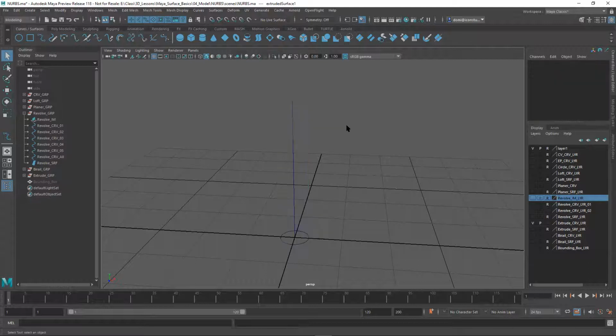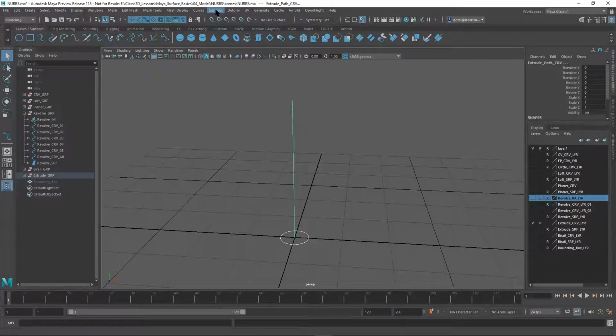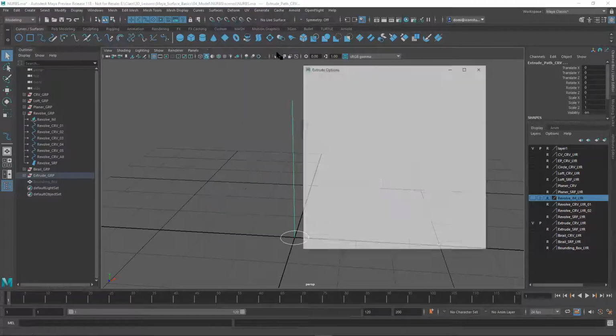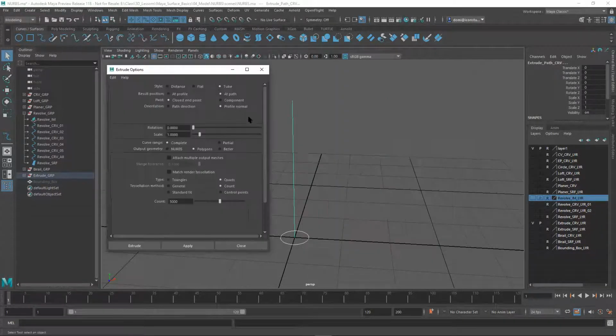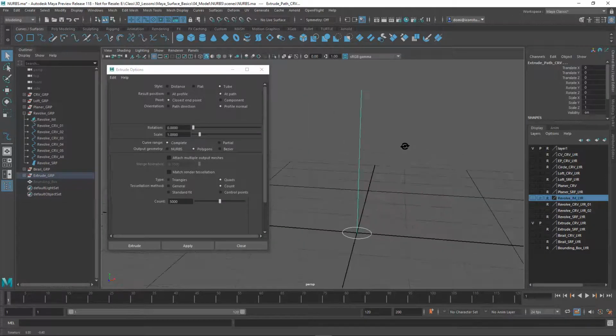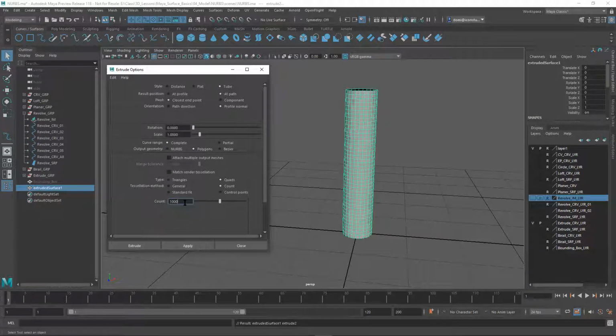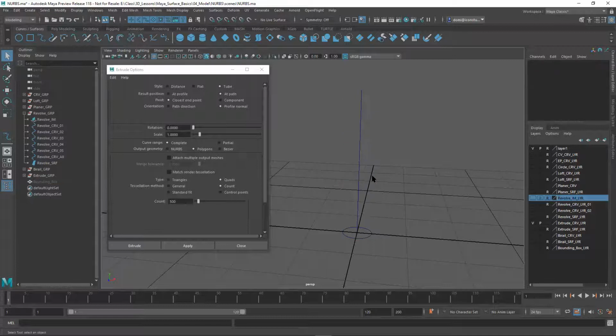Let me check something here. I'm going to pick this, pick this. Did it extrude? Let's see. Ah, I already had this set up, oh, you know what? It will remember your last polygon set. I was noticing it looked pretty dense there. So I don't want that thing so dense. So I really just want it maybe 1,000. Probably even too much there. Let's go 500. Oop, have to delete it first. Okay.